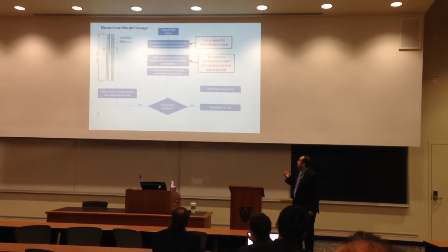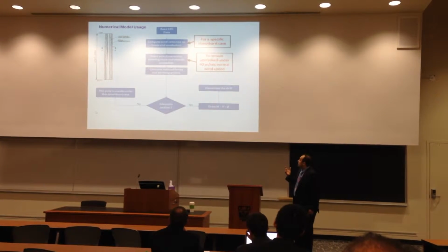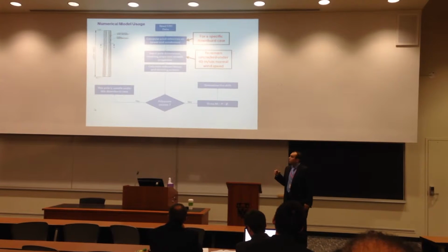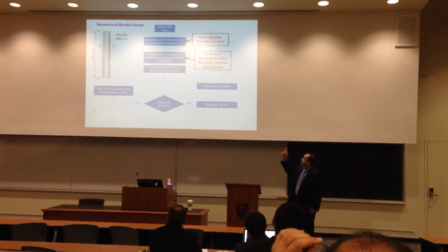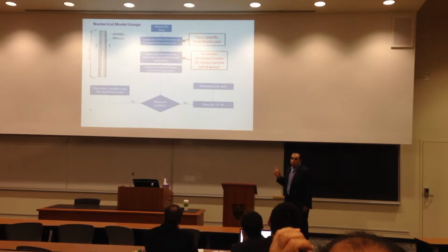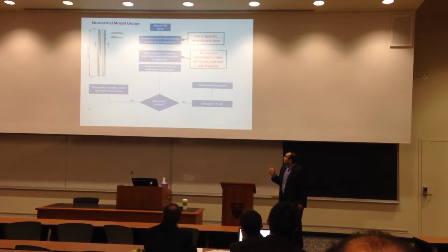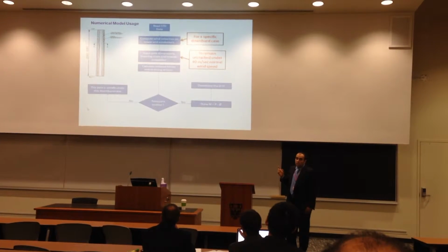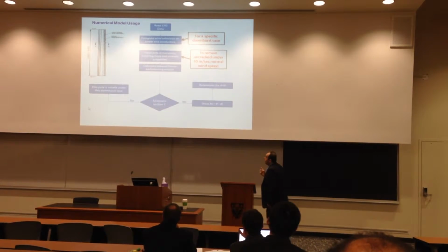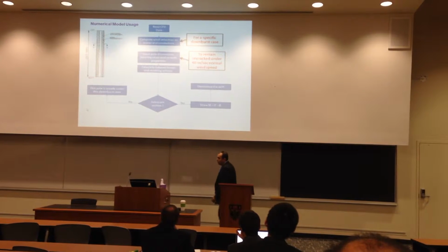If the section is adequate, we draw the moment curvature diagram under a certain compression force, and we determine the total drift under this specific downburst case. If the cross section is not adequate, we say that this pole is unsafe under this downburst case, even if it is designed to remain uncracked under a normal wind speed of 40 meters per second.